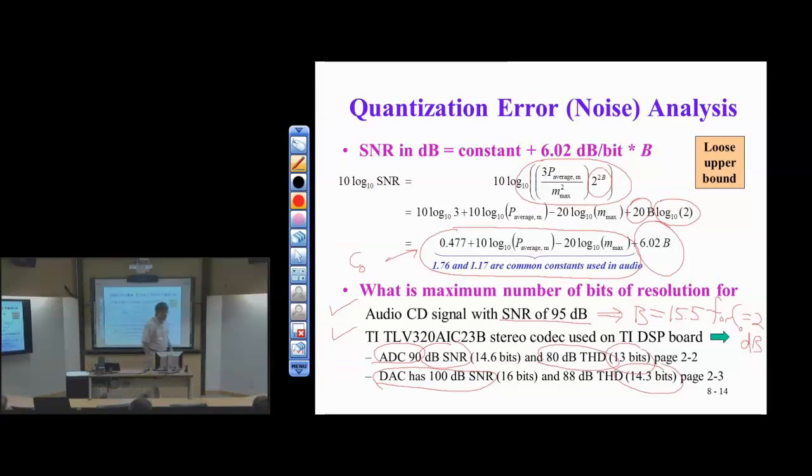So the automatic gain controls are factoring this into how much gain they're going to apply, because you want to put more of your signal in your MSBs, right? This is telling you that for a certain test signal, they measure the SNR. They send pseudo noise through, and they measure the SNR that comes out, because they know what the input signal should be. I'll give you the measurement for total harmonic distortion on the next slide. That will help, I think, a lot. Both of these measurements are from a test signal.